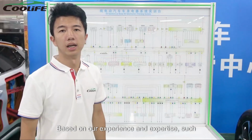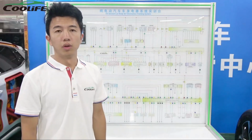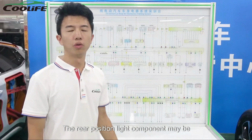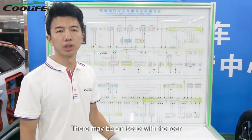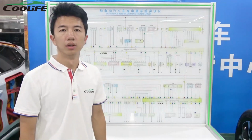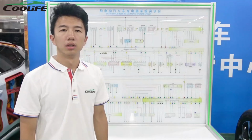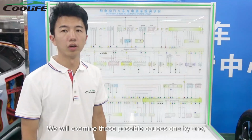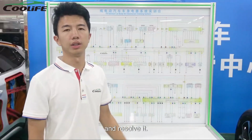Based on our experience and expertise, such issues are typically caused by the following. The rear position light component may be damaged. There may be an issue with the rear position light wiring. The controller may have a malfunction. We will examine these possible causes one by one, identify the root issue, and resolve it.